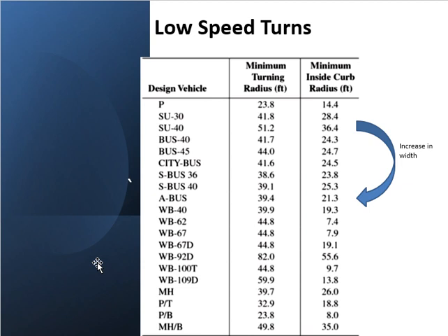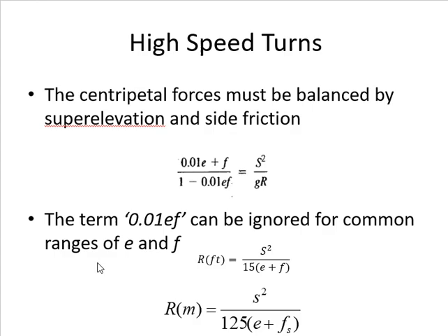Okay, so you can see on the top, the difference is very small, right? It's less than 10 here. If you look here, it's more than 30 feet. Why? Because the vehicle is heavier, bigger. So the two radii are mentioned so that you know that you need to do some widening, extra width. They're showing the extra width we need.